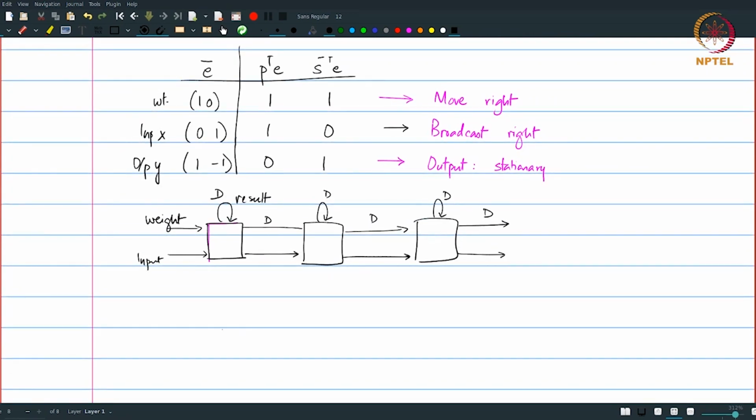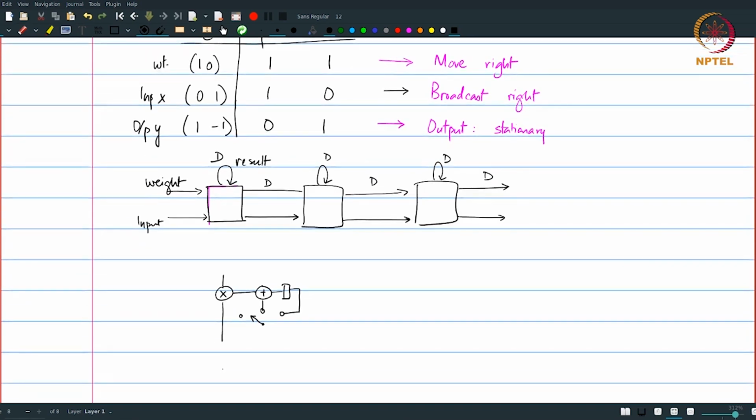Redrawing this, I can think of it in terms of the multiplication and an accumulation and holding the value that all needs to be done in the same place. The switch that I have over here essentially allows me to switch between either a 0 in order to reset the value every 3 clock cycles, or the previous accumulated value to come back into the design. And what we have over here is the other input to the multiplier essentially corresponds to the weight value, which will take the sequence W0, W1, W2, W0, etc.